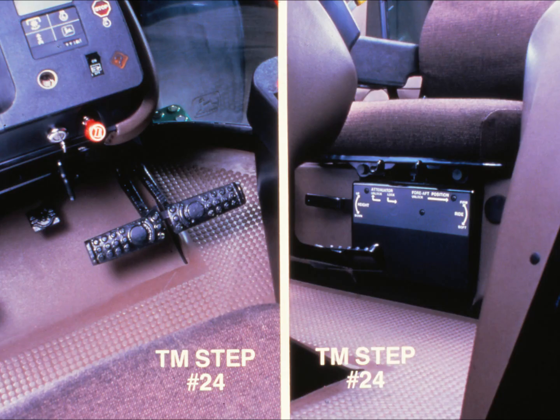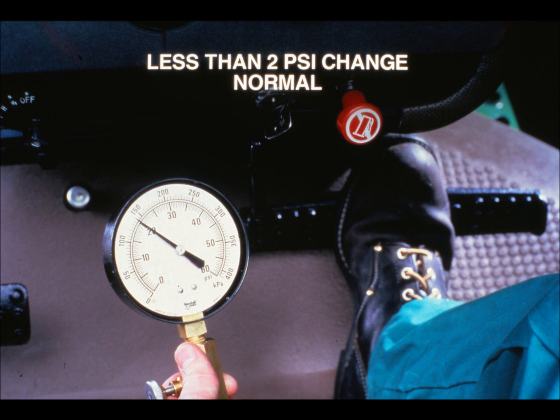Step number 24 is a series of checks for leaks to sump from the brake valves, differential lock valve, and seat valve. Run the engine at 1,000 RPM and step on the brake pedals one at a time. Then, step on the diff lock pedal. Finally, move the seat height control lever from high to low. Record lube pressure as you operate each of them, the brakes, diff lock, and seat valve.